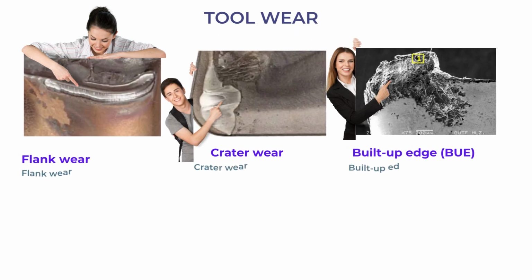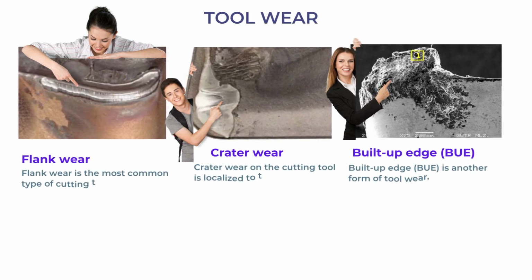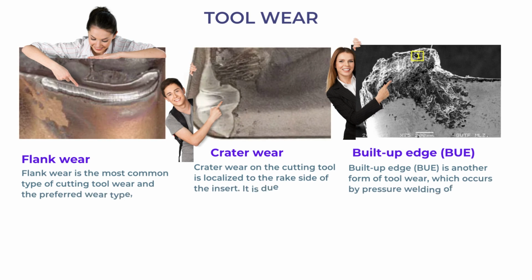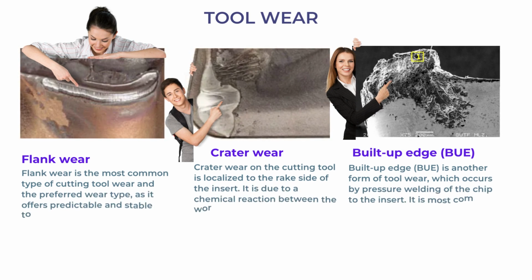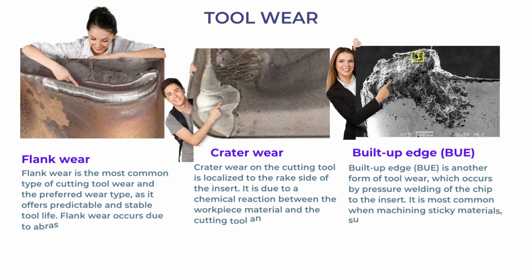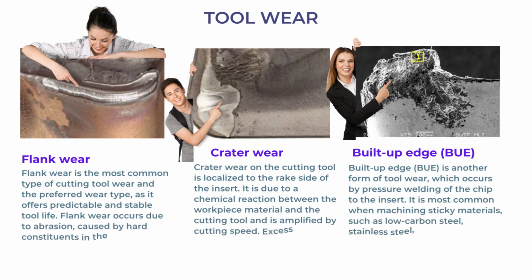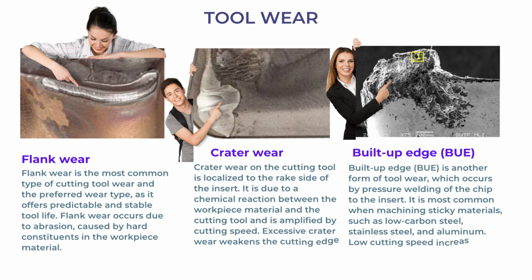Tool wear. Wear is the loss of material that occurs on the insert's contact surfaces. Although we take all the necessary precautions to use the inserts within the maximum limits, wear occurs on the cutting edges. During the machining of materials, all inserts wear and continue until they complete their life. In other words, tool wear is inevitable. During chip removal, different parts of the cutting tools are exposed to different types of wear, and as a result, the life of the cutting tool is reduced, it becomes dull and the insert breaks.